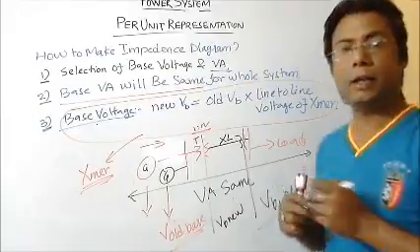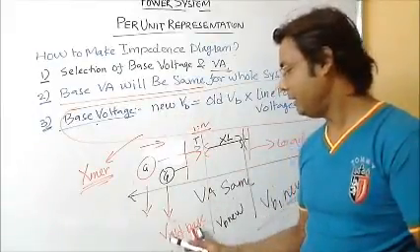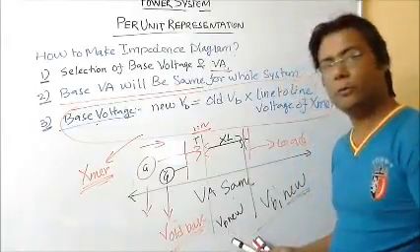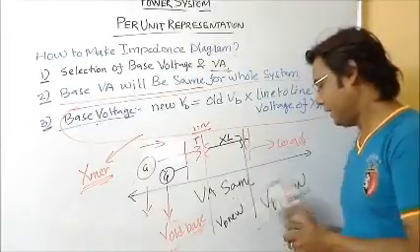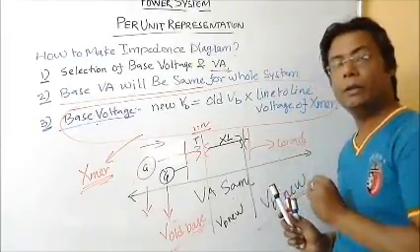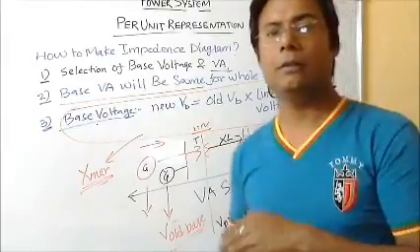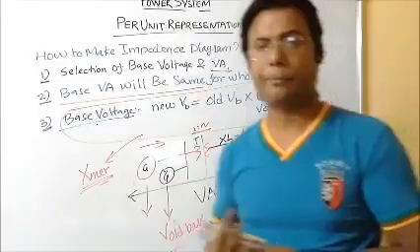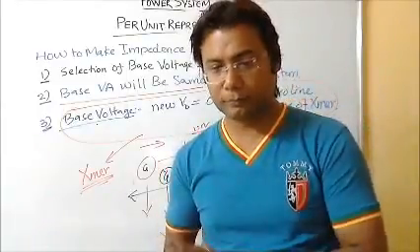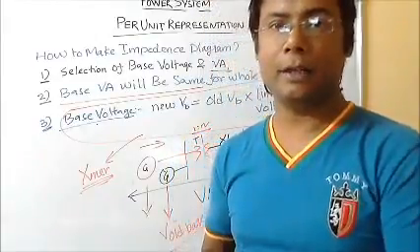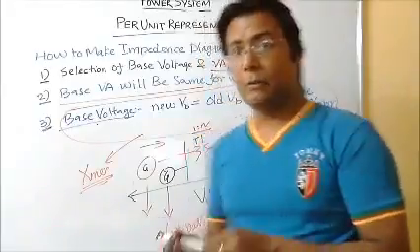So according to our transformer, base voltage changes. Here it was old, then it came to new, then now the new will become old for the same thing, and a new VB1 will come after a transformer. So n number of transformers will be coming, so n number of new VB will be coming. That is the way we are describing an impedance diagram over here.